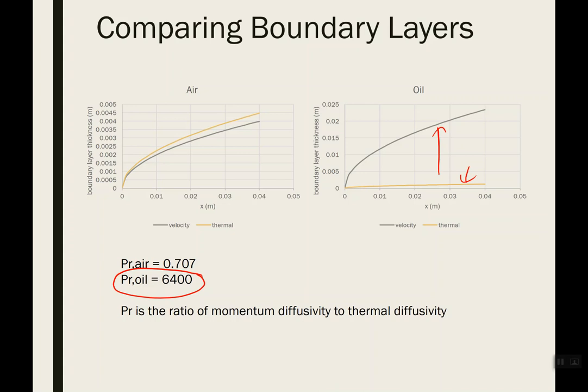Great, yeah. So if we have... Alex said the velocity boundary layer thickness is where the velocity reaches 99% of the bulk fluid velocity. So if we had uniform flow coming and encountering a simple object like a flat table, that uniform flow is going to develop a velocity profile, because the flow immediately closest to the surface is going to have a velocity of 0, assuming a no slip condition. So getting from that 0 velocity for the layer of fluid immediately touching the table to the bulk fluid, there's going to be some transition.